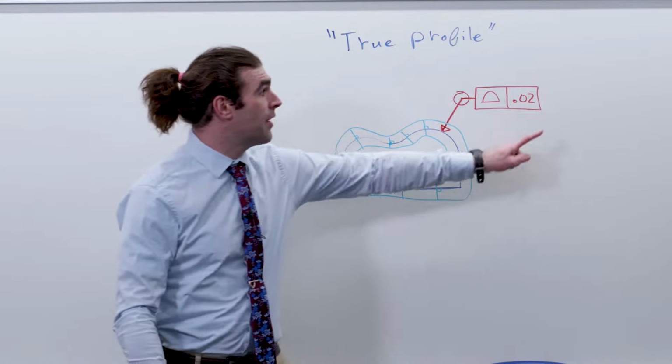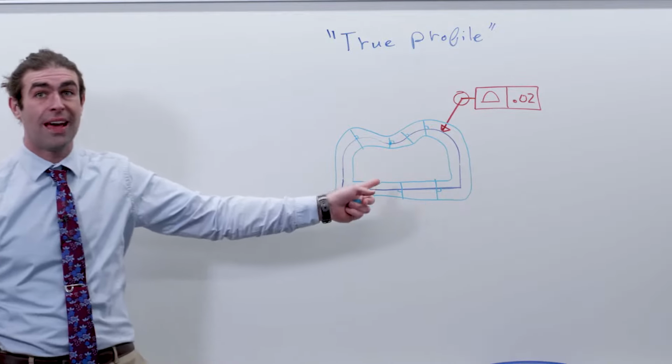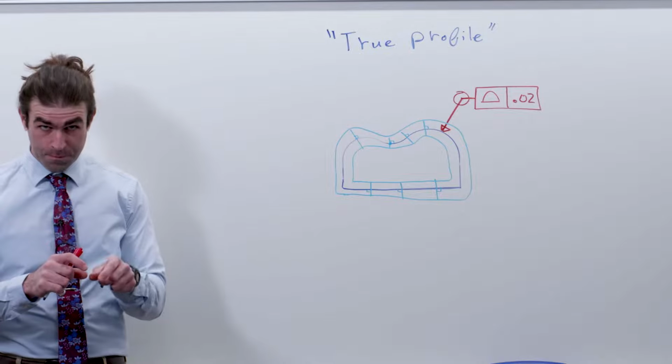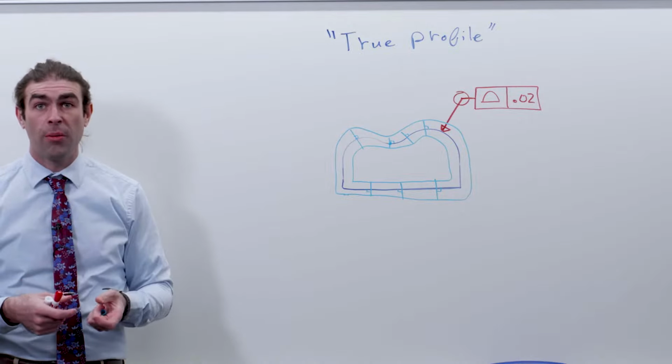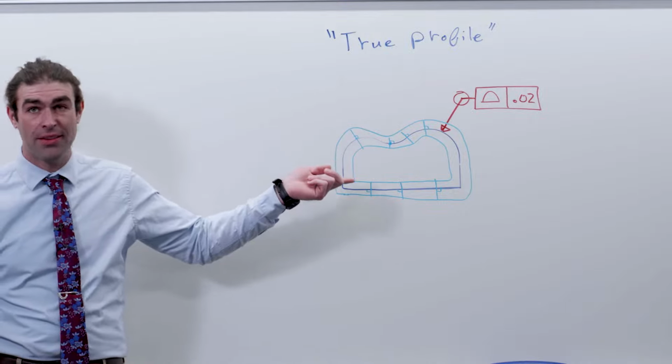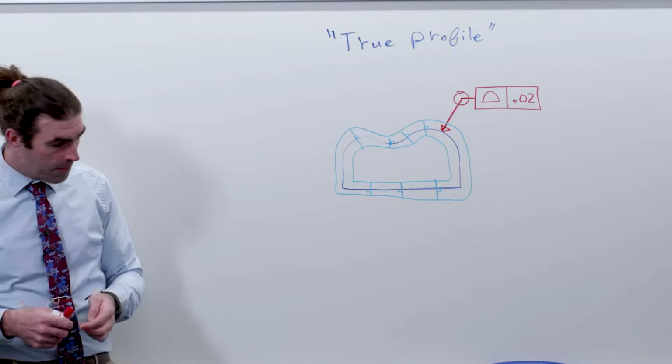Now, if you notice, there's no datum references on here because I haven't called out any datums on the part. This would just control the form of the surface and the size of the part because there would be basic dimensions on here.